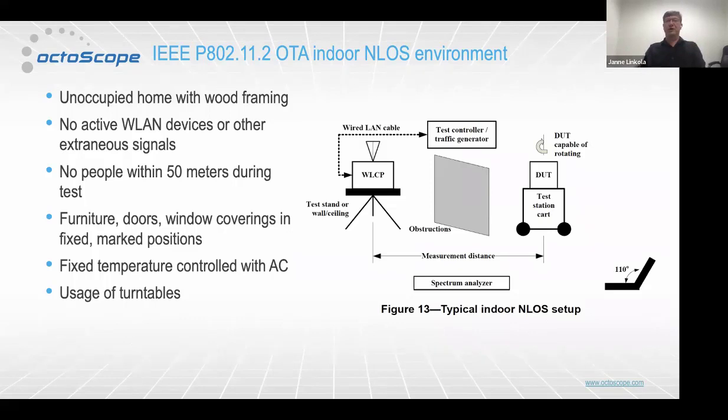We had a whole other presentation a couple of weeks ago where Lee talked about antennas. And so anyway, to rule out any scenario where we accidentally direct, let's say, the null to the direction of the link of, let's say, the throughput measurement, they recommend that you use turntables to rule out any kind of effects like that, and then you average those results out. In fact, they talk about two different types of turntable procedures. They have what they call stop motion turntables, where when you run the test, you don't move the turntable, but then in between tests you turn it, and then they have another protocol where the turntables are moving. There's an access point, the turntable under the access point, another one under a station, and they even talk about at which rate these turntables should spin.